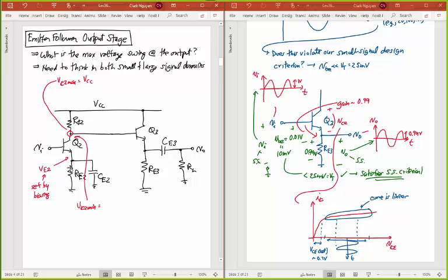That's a bias point there. And so I could say that VC2 min has to be equal to VE2 plus a VCE2 sat voltage. So it's about 0.2 volts higher than what VE2 is there. That's going to be my minimum voltage right here at that point.